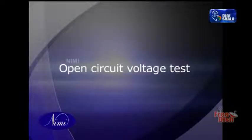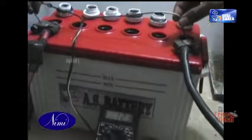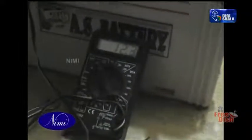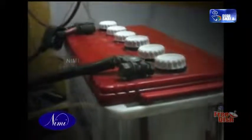Open circuit voltage test. Connect the leads of the DC voltmeter to the cell terminal. Take the reading from the voltmeter and record. Repeat the procedure for all the cells and record the readings. The voltmeter should read at least 2.2 volts per cell. Recharge or replace the battery if it is in poor condition.